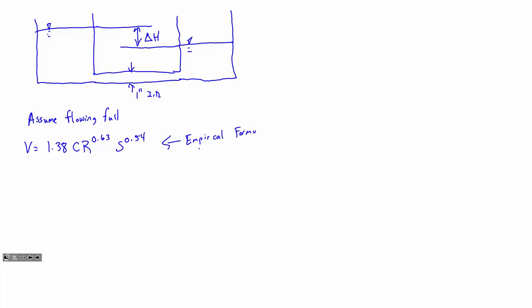And we can see here just in terms of the roughness coefficient, our C value was 150, right? But our Manning's n is normally 0.01 to 0.03, something in that range, right? So you see here that this is multiplied by this roughness coefficient as opposed to divided by that roughness coefficient.